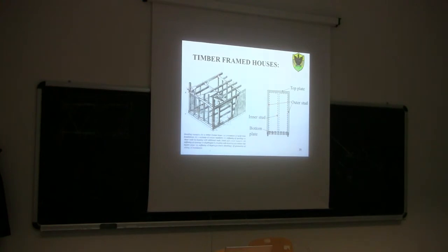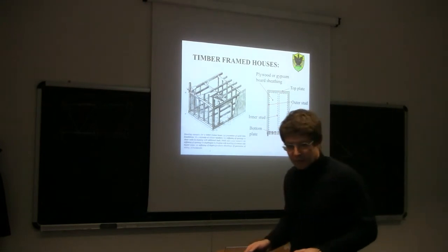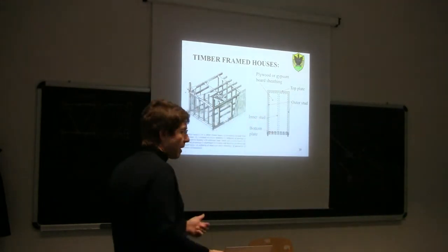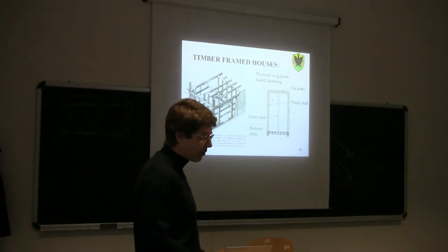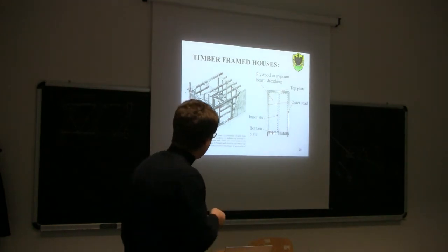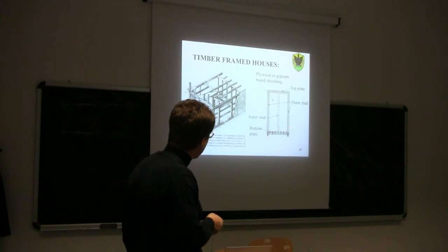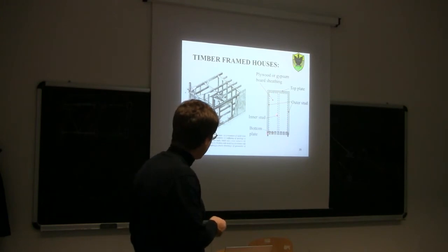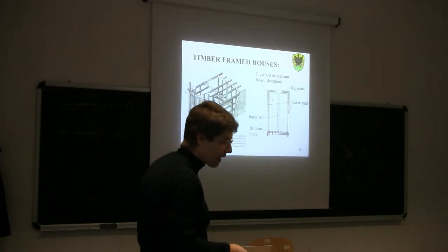Okay? So again, this is a frame with pin connection, and on top of this frame, on one side or both sides of this frame, there is a sheathing panel made, we said before, of particle board or oriented strand board or plywood, and this sheathing panel is nailed onto this frame. So it's nailed along the plate, top plate, bottom plate, and along the whole studs.